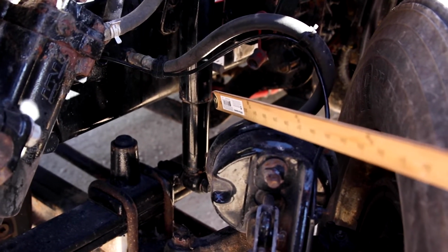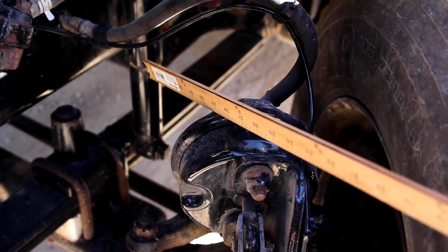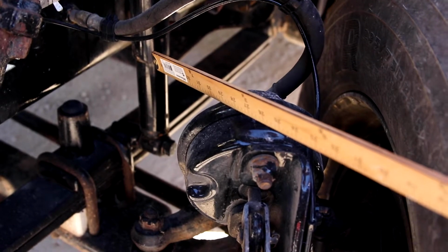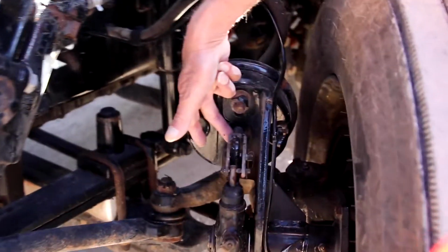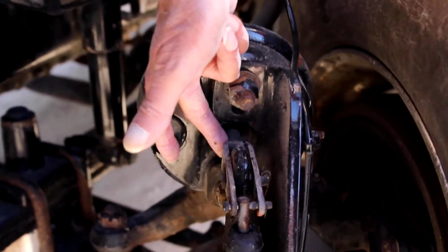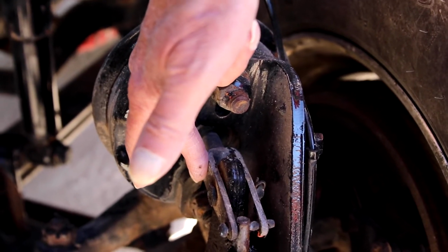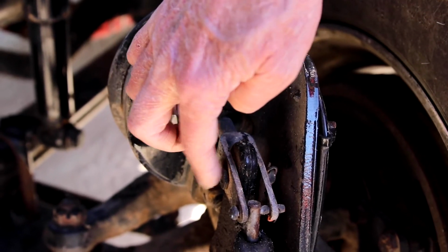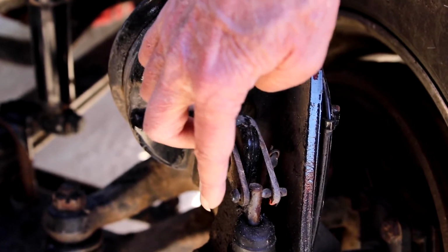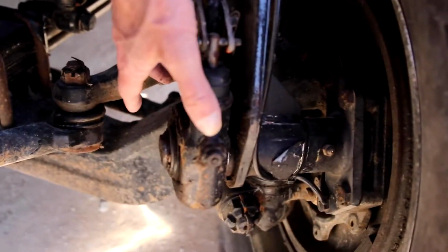This is your brake chamber. You want to say it is mounted securely to the vehicle. It's not missing, damaged, or broken. No audible leaks. Then we're moving to the brake mechanism itself. This is your push rod back here where my finger is. Mounted with the clevis. This U-shaped piece here is called a clevis. These are clevis pins that attach to the slack adjuster, this large part right here.